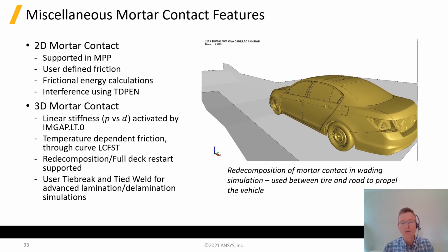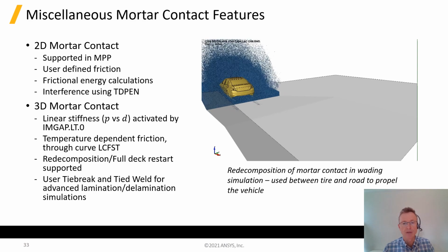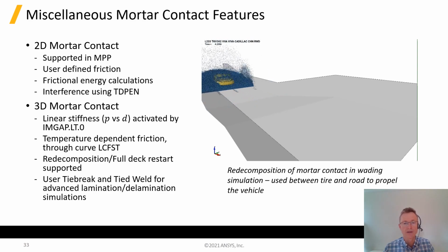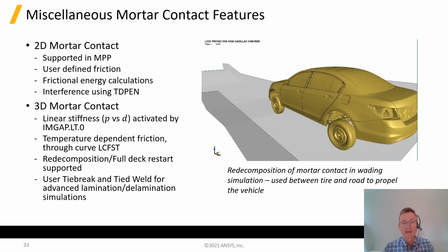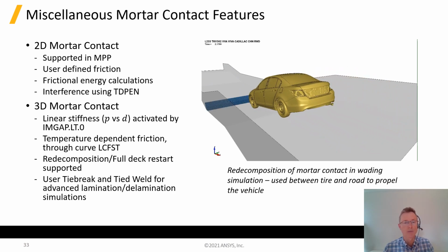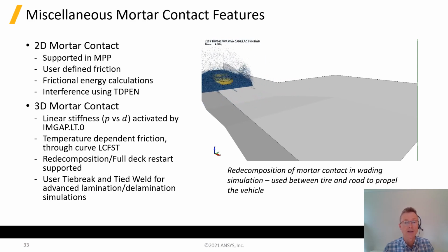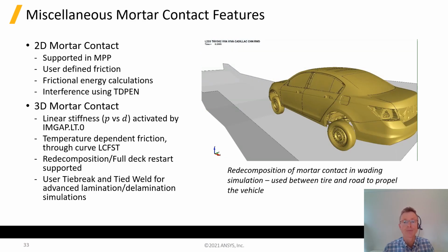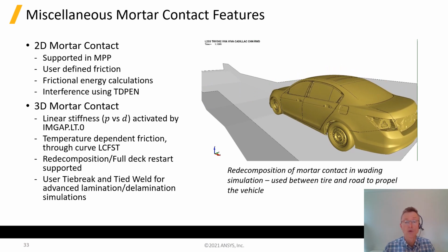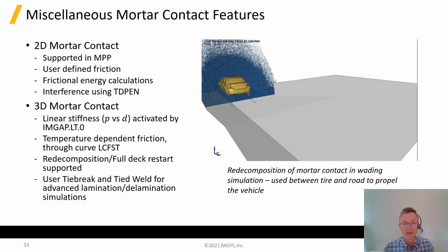The particular point being illustrated here is that for this type of analysis, the SPH particles representing the water spray all over the place, and it's more efficient to redistribute them between the different MPP processes at certain time intervals during the calculation to try to keep the near neighbours together. And the point here is that the mortar contact is also working with that redistribution between the processes.